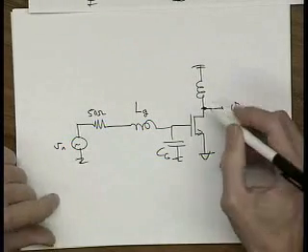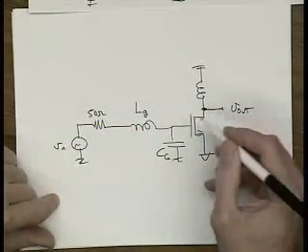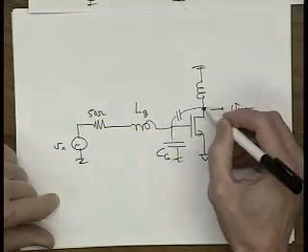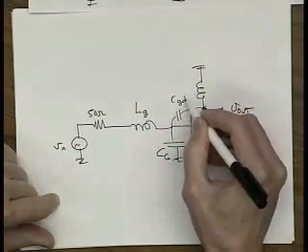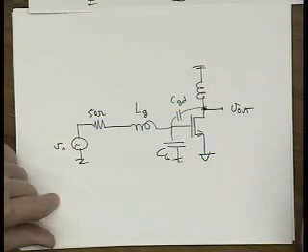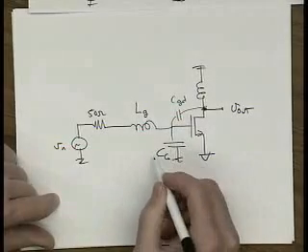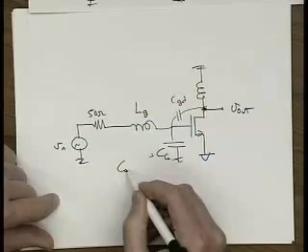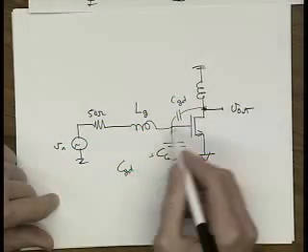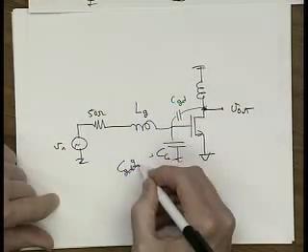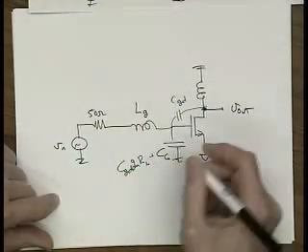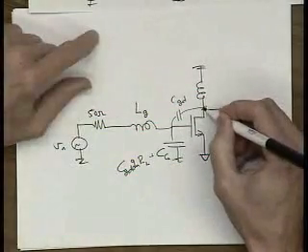Okay, so for this circuit, remember there's a capacitance associated here, good old CGD, because I haven't made a cascode here, okay? So we could put that down here, 1 plus CGD times the gain of this stage, right? GM R load. And the question, what's R load of this stage?